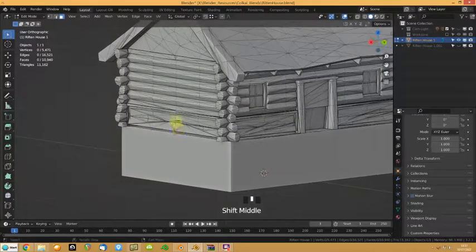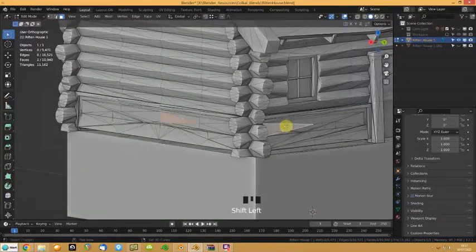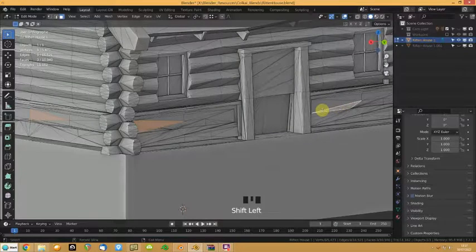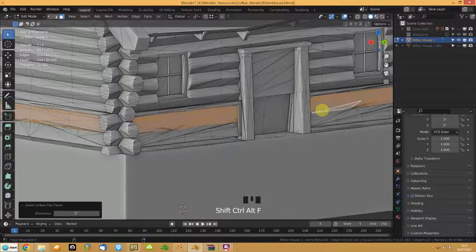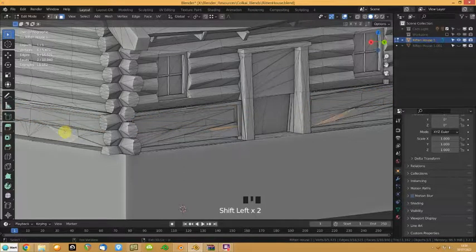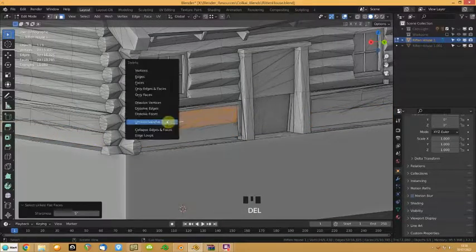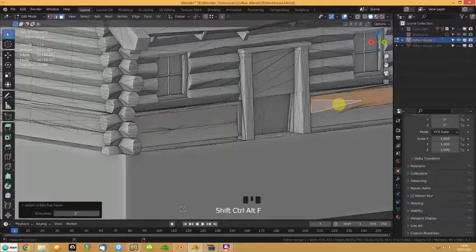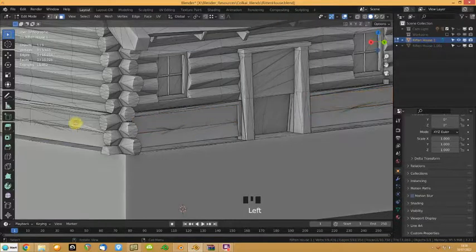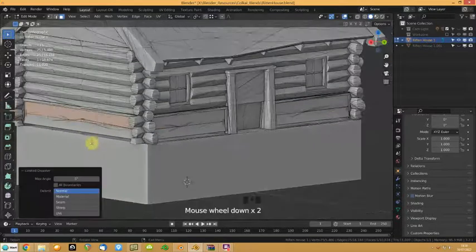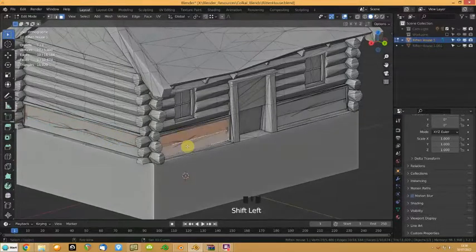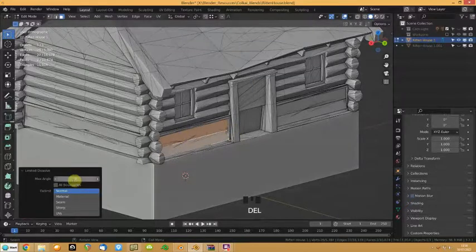Now we're talking about bad geometry. Here's a case in point. Let's select those 3, and you can select multiples with click and shift click, as you can see. Then I'll flat face them, select these, and limited dissolve. The reason I did that in sections is that if I chose both of them and did limited dissolve, depending on the angle that limited dissolve had, it might choose to flatten that.